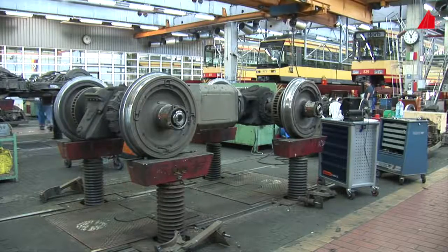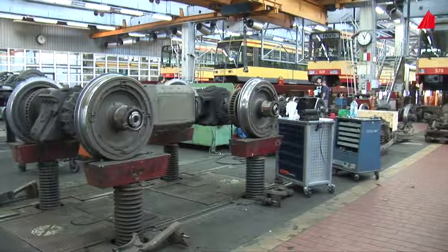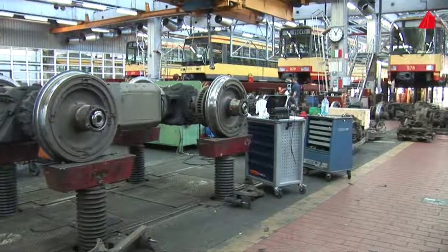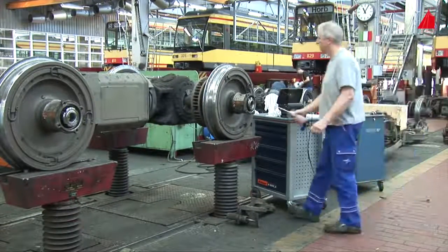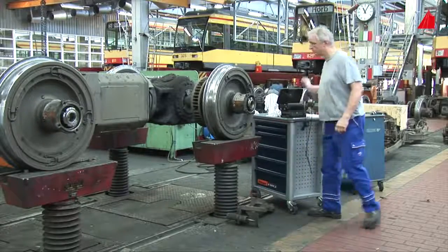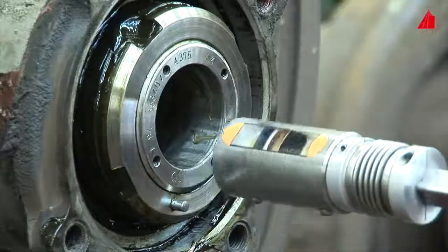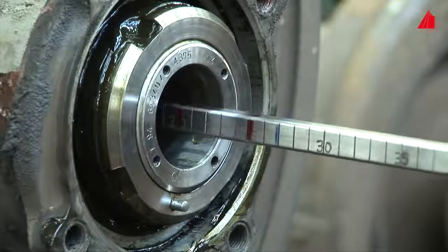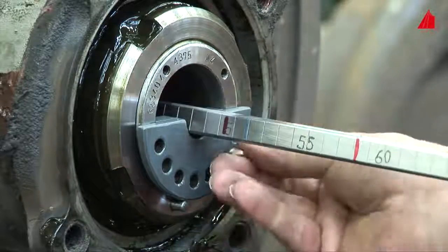This is one of the bogies, jacked up to comfortable working height and prepared for ultrasonic inspection. Special attention is given to the wheel axle, among experts known as wheel set axle. It has been designed as a hollow axle. This saves weight and facilitates the ultrasonic examination. The material tester applies a suitable oil as a couplant into the bore of the axle. Now he takes a special probe designed exactly for this purpose, inserts it carefully into the bore with a mount, and evenly spreads out the couplant by turning and pushing. He has accurately marked the most important examination points at the mount.